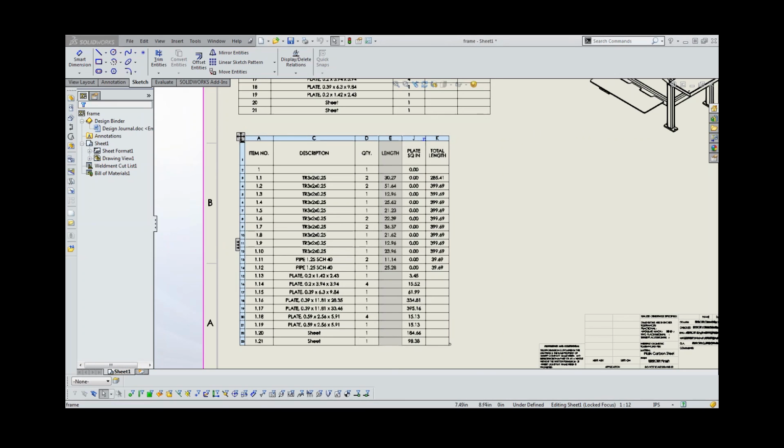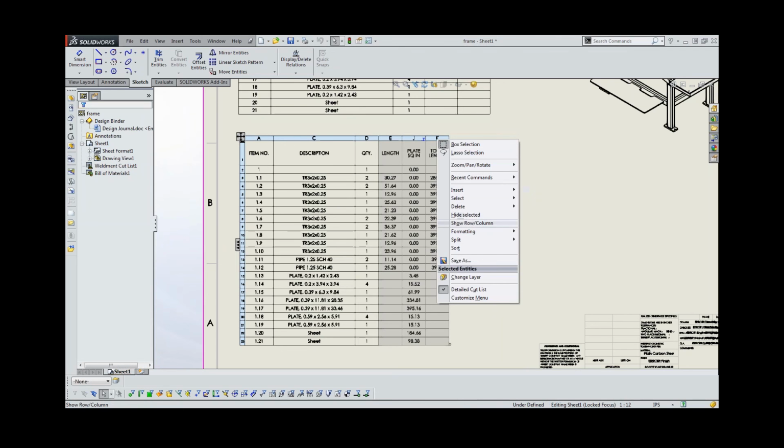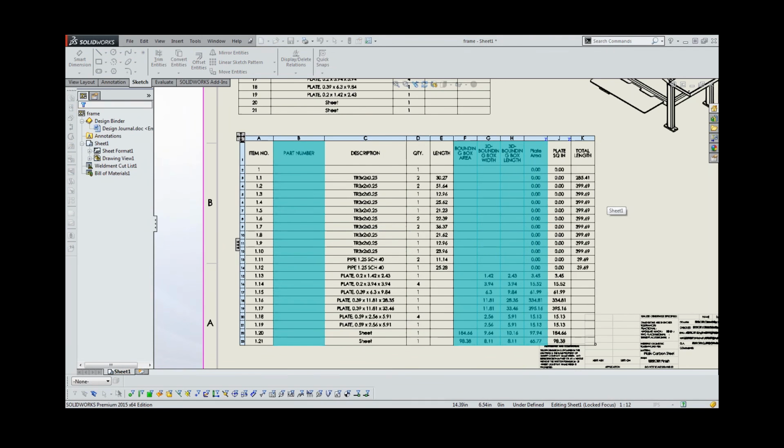the bounding box dimensions to get a total on that one. And so I'll unhide what I've got here. So you can see here I brought in a bounding box, and that populated for my 2 sheet metals. And then I brought in those calculated bounding box dimensions and created a calculated field for those. So now I've got my square inches for my various plates and gussets.